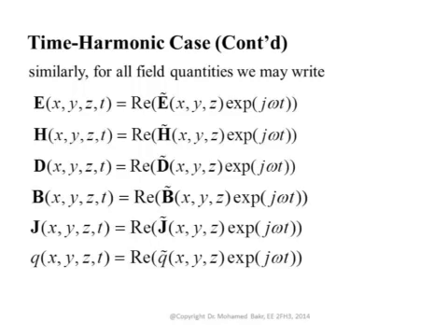This actually simplifies the analysis in many applications where you assume all your sources are only sinusoidal. So if you have an antenna, and this antenna is connected to a sinusoidal waveform, it's only radiating sinusoidal waves. So everywhere the electric and magnetic fields will be sinusoidal. They will have their own amplitude and their phases. I don't have to worry about the term e to the j omega t. I can add that later and then recover the actual time domain quantities.